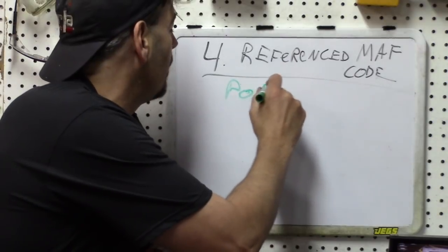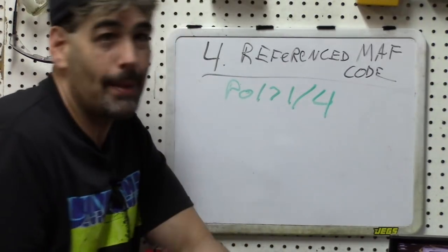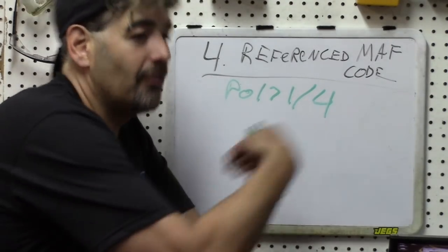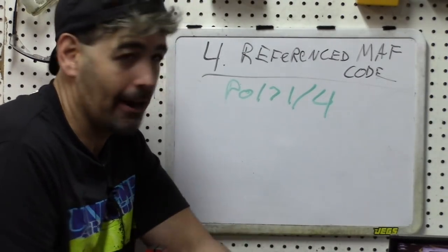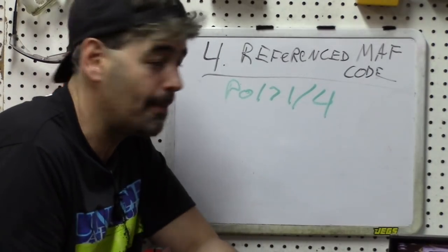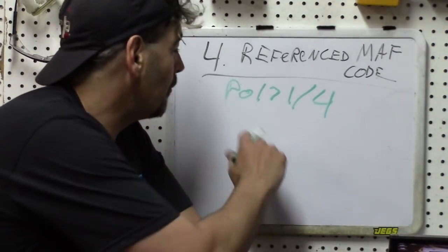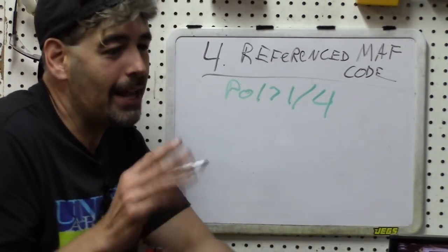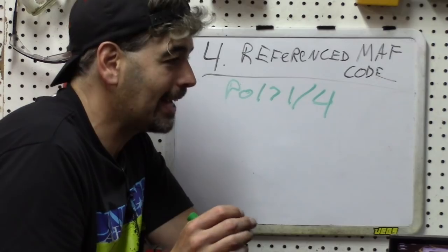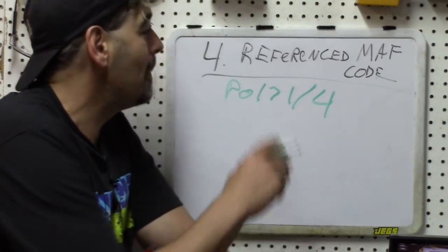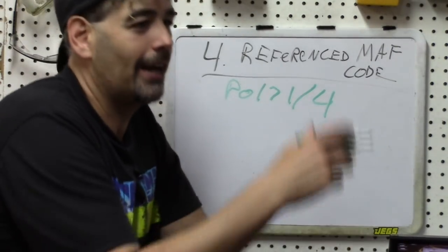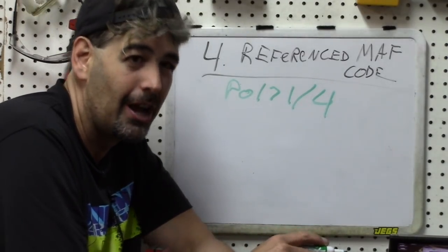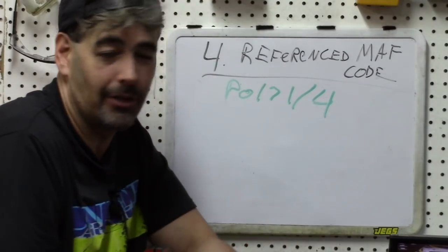measurement with the incoming air. They're going to start pointing to the MAF sensor. Now, don't forget, replacing the MAF sensor erroneously is not a $400 mistake. It's more like kind of a $700 mistake because you've replaced the plugs, wires, O2 sensors, everything else before. So by the time you got to the MAF sensor, most people have already dumped $300 into trying to solve their problem.